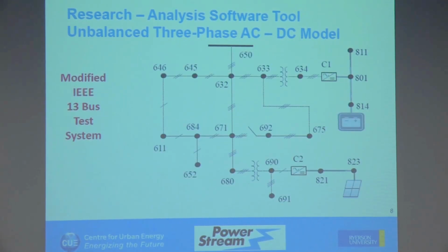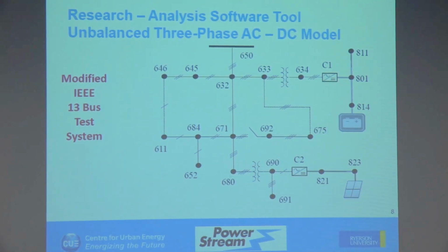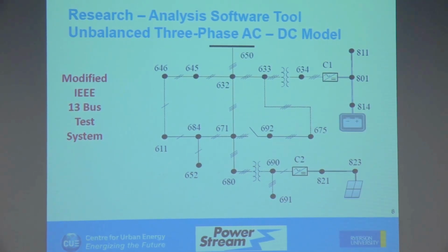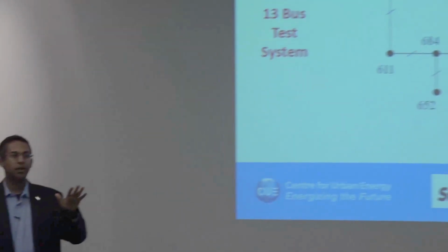So once we put that in, then it becomes very simple, right? It is just a regular power balance equation with the Y matrix made out, where wherever you have a converter, the pi model of the converter is used to populate those terms of the Y bus. So now I can write the whole power balance for the entire microgrid with AC and DC, where AC is three-phase and you have DC buses as well in the DC network, and the pi model is able to relate or connect the AC buses to the DC buses, the pi model which we proposed just now.